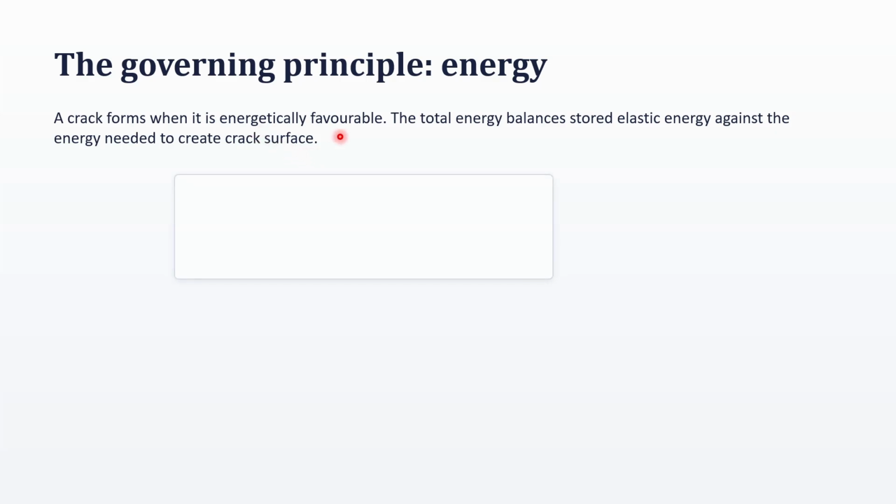So essentially we have the internal bulk energy functional as this. This is the internal strain energy per unit volume multiplied by dV, integrated over the domain, plus the fracture energy, where Gc multiplied by small gamma was what? Small gamma was the crack surface energy density, and Gc is the critical energy release rate, which is a material parameter.